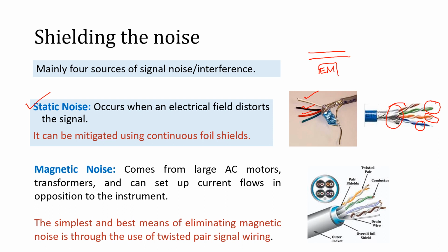So you can feel that whenever there is a power supply on and off, there is a momentary noise in your TV. Okay, so it means there is a noise which is static and it's permanently there as long as that source is very near to this wire. So that is a static noise, and it is always due to electrical fields which are very near to the wires.